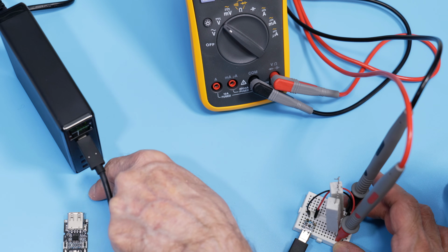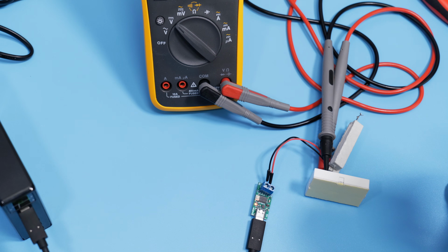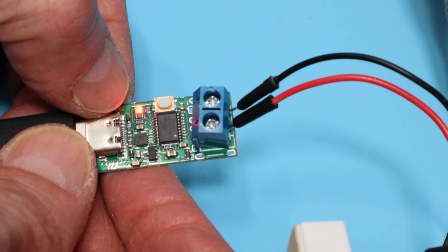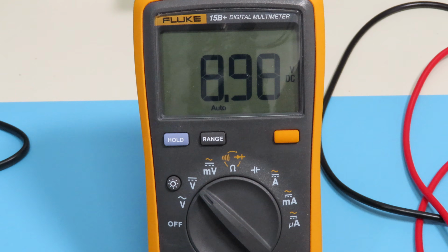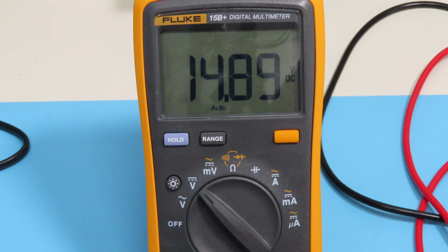Now we're going to take this module, and we're going to put it to the test. So I've got the ZY12PDN hooked up to my USB-PD power supply and to my test load, and the voltmeter says I'm getting 5 volts out, which is also indicated by the red LED. And if I press the button, the LED changes color, and as you can see, I get a different voltage. And I can cycle through all the different USB-PD voltages I've got here. Here's my 20 volts at the top, and then I'll go back to the 5 volts again.